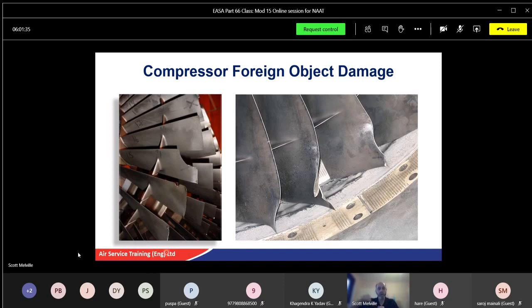They put a bit of pressure on it, they've turned it, they've actually bent the probe at the end, which obviously doesn't seal properly, and that lets hot gas come out. Because the blank doesn't just blank the casing, it also blanks, especially for turbines, the turbine casing inside. And if you don't put it in properly, that blank will not seal off the access hole for the turbine. Well, where's the turbine gas going to go? Straight back out into your LP cooling duct, and that'll probably give you a hot warning light in your cockpit.